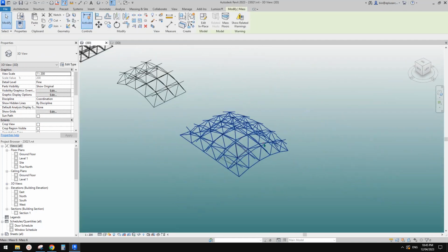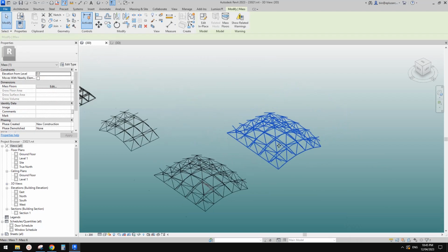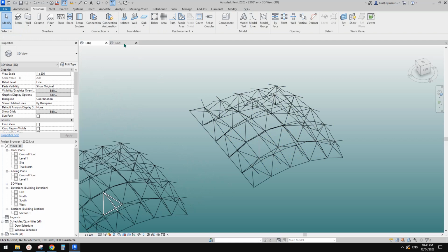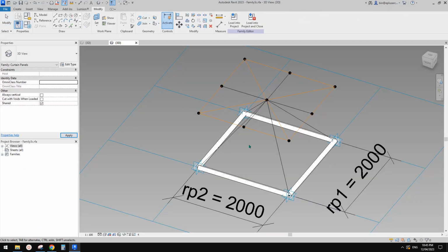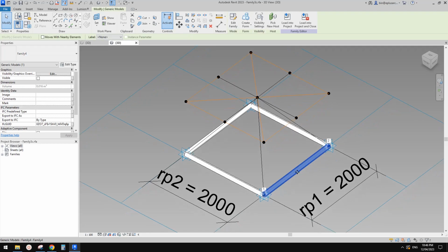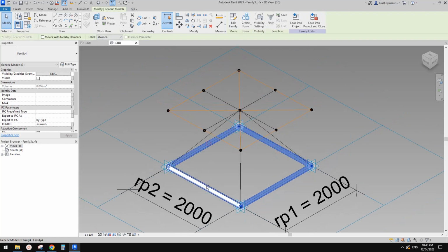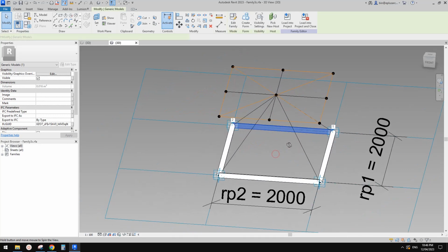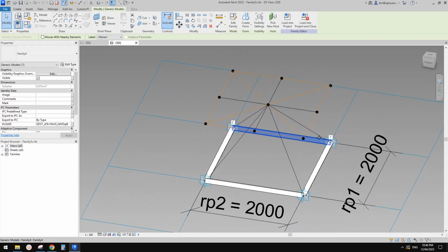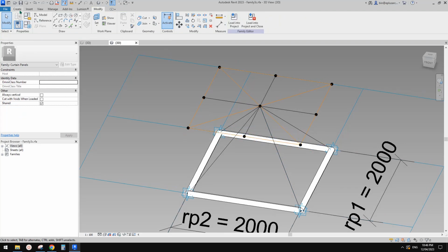Or if you don't want to do a structure element, you can also use a pattern based family. So if you just go back here, this is an adaptive family we did yesterday. So basically we just need to create one, and then we can place onto that. So first let me just check the box visibility so we can see them, and also just place some on these model lines. So CS, sorry, we can't use create similar here.